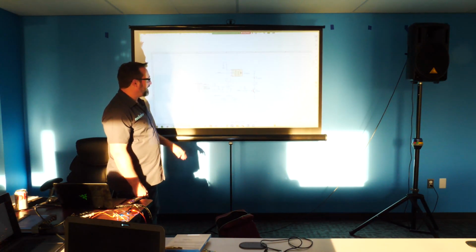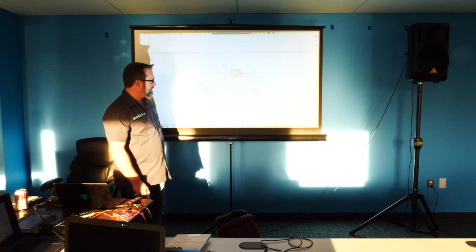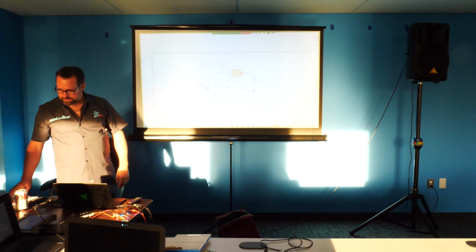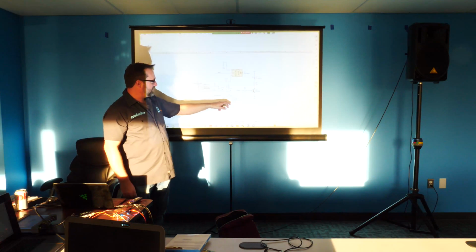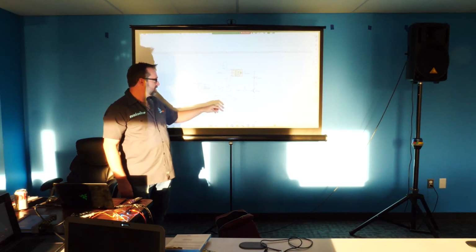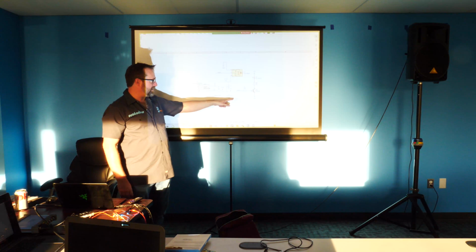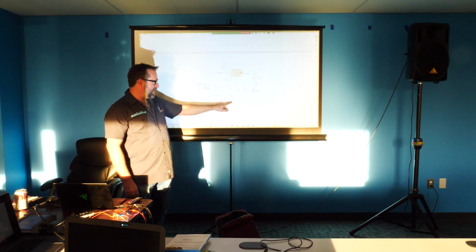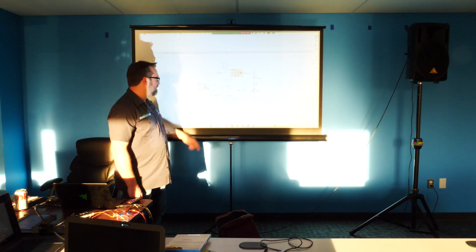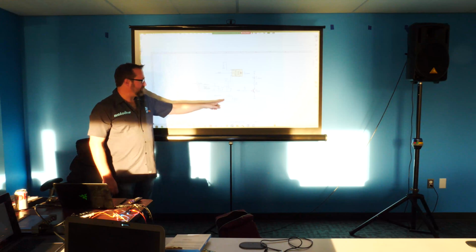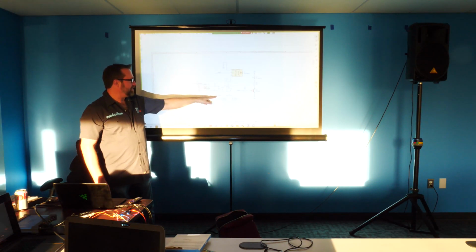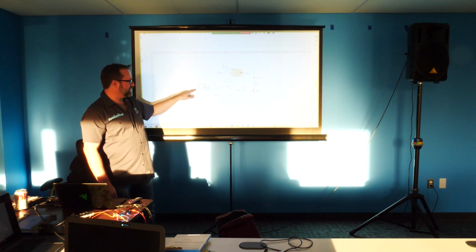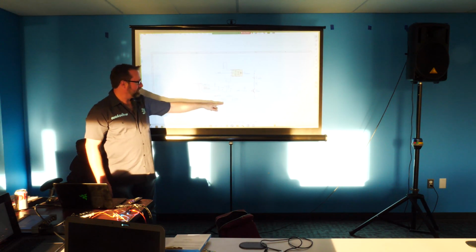The other thing that we have is a button, and basically it has 4 pins, and they're normally not connected. Okay, so there's 2 pins normally not connected. NO means normally open, and we only need 1 signal, so we run it from this side. That's the button input. So that button input is going into the Raspberry Pi Pico.